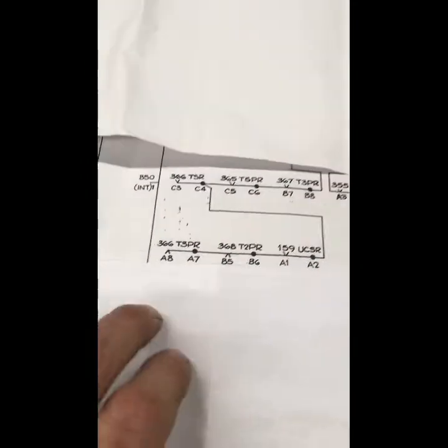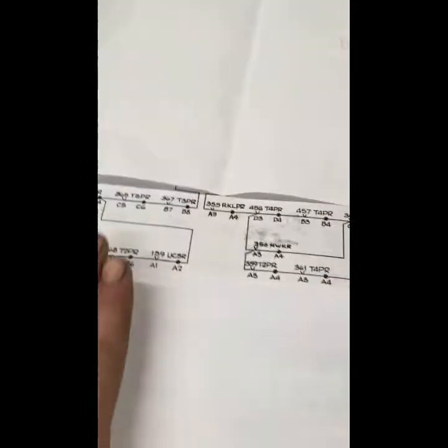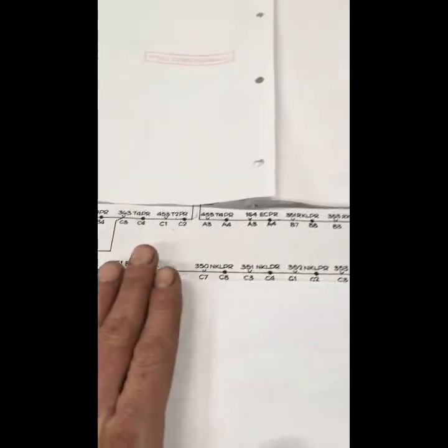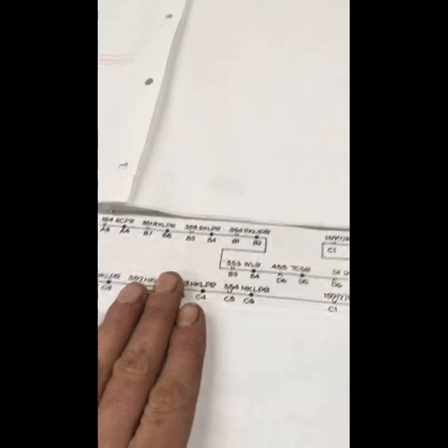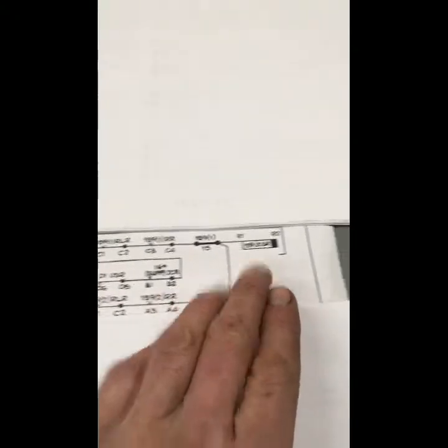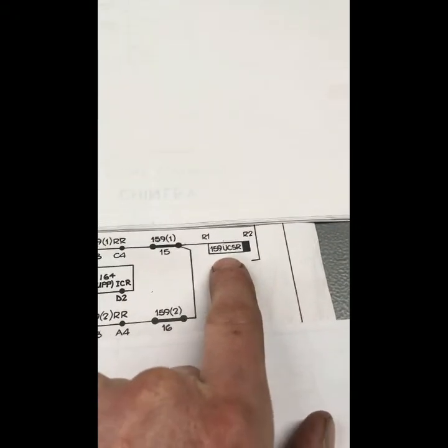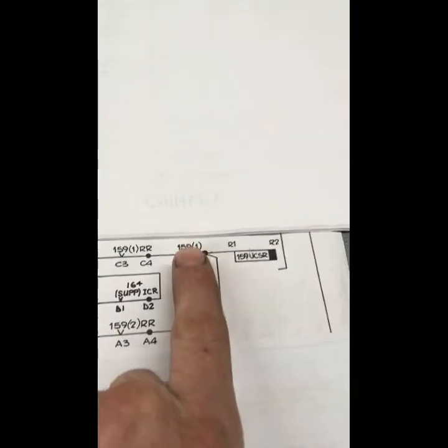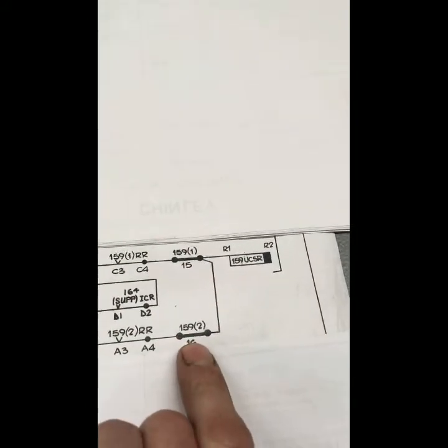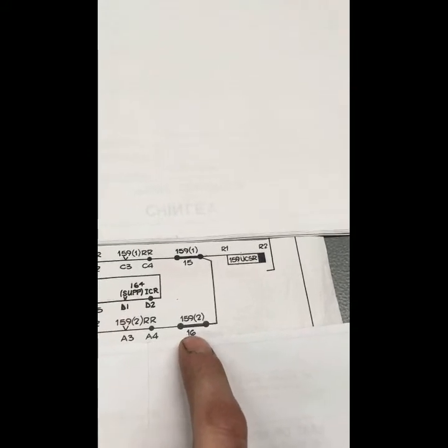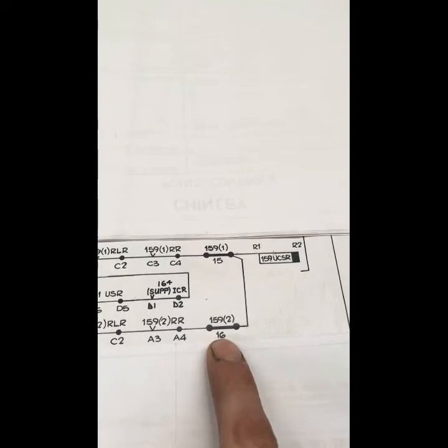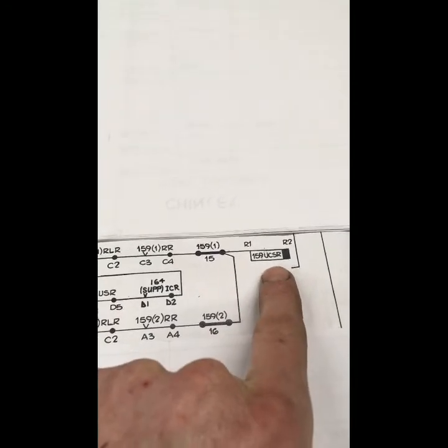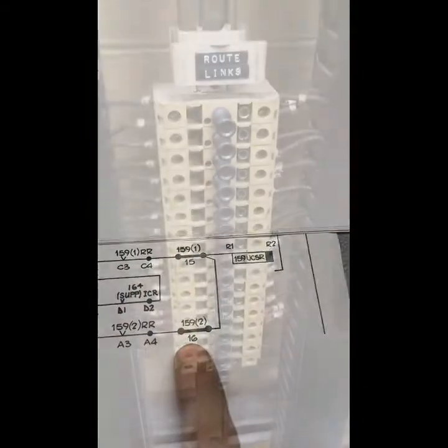Finally, now we're at the end, with all our controlling relays being in the correct positions for our points, our tracks and our other lamp proving and signals, we can clear our route checking or proving stick relay, and that will stick up and hold. These links here are our route links, so should we need to disconnect for signalling works or permanent way works, we can pull those pins out, and that will prevent the UCSR from therefore clearing the signals out on the ground further down the line. And I'll show you them in a second.